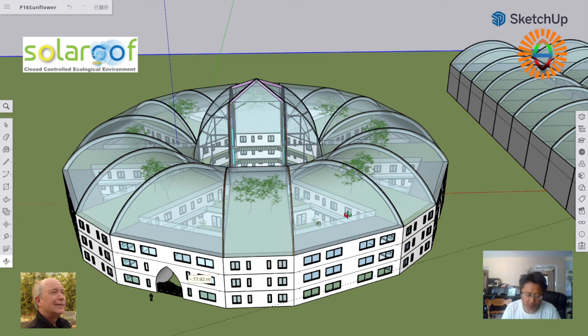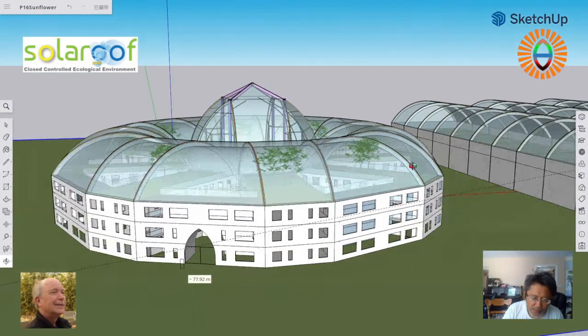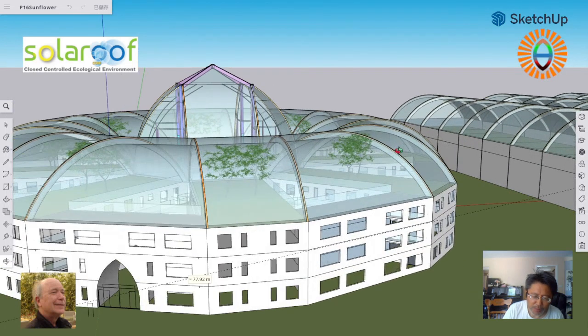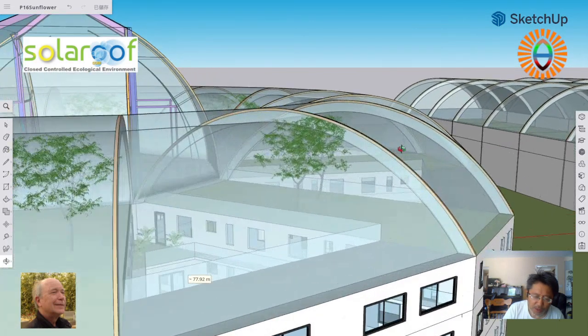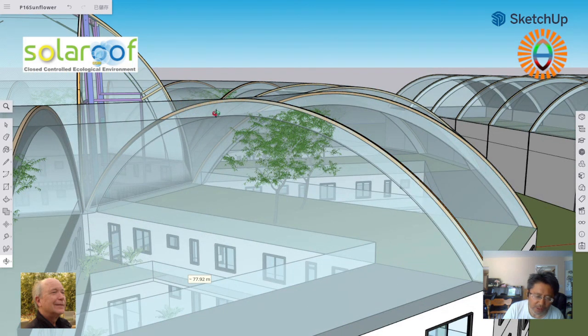We simply spray water in the double layer cavity. By the way, I need to point out, see here, we have 1 meter separation between the outer layer and the inner layer. This is the cavity. You can spray water to cool the space, and then cool the entire roof. So this is what we call a cold roof system.